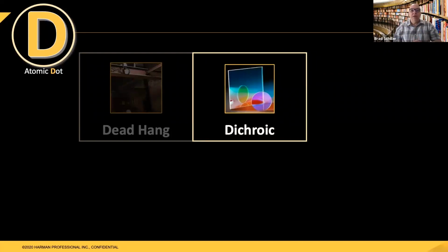Plus, one more interesting property of dichroic filters is that as you angle them, you can change what wavelengths are passing through. Now, a different brand called Vari-Lite made use of this a long time ago in the classic VL5 fixture, where they used Dichrotune, their technology that would turn the blades of dichroics and actually change the color or the hue coming out of that filter. So dichroic filters have a lot of different uses. And incidentally, they were originally created and developed by NASA for space visors and for protection on spacecraft windows. So dichroics are really fun and really cool things that we use in our industry.